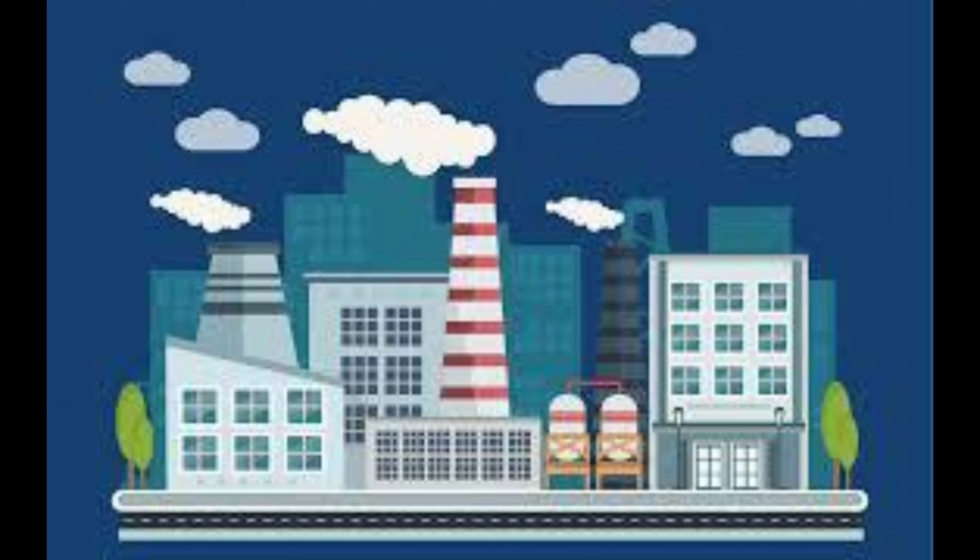The treatment of industrial effluents. There were three types of treatments. They are known as primary, secondary, and tertiary. The primary treatment is mechanical, which means screening, grinding, flocculation, and sedimentation. The secondary is a biological process. It is the planting of trees, increasing grass cover, rainwater harvesting, etc. The tertiary is biological, chemical, and physical processes. It also includes the recycling of wastewater.